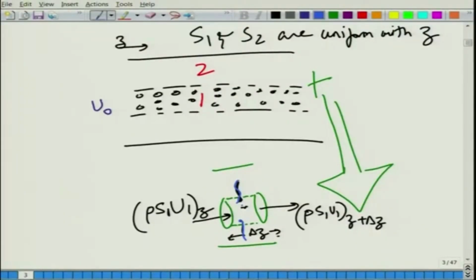You can consider wave propagation through individual holes through a very complicated analysis, maybe as an array of resonators. But the approach that we are following right now is very easy and it is used a lot. The other approach, I am not quite sure, people might have done it, but this is the most popular approach of modeling the perforates by means of an impedance expression, like a permeable surface.